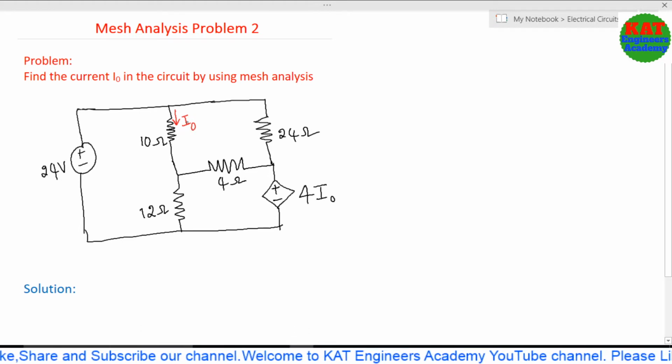So how to evaluate this I0 current is a simple procedure. First you have to evaluate the loop currents. Here we consider small I1, I2, I3, since we have three loops and will get three currents. I0 is related to the first loop as well as the second loop, so finally I0 is the first loop current minus the second loop current. So first we have to know I1 and I2 by determining the mesh currents, and finally evaluate I0. This is the procedure to solve the problem.